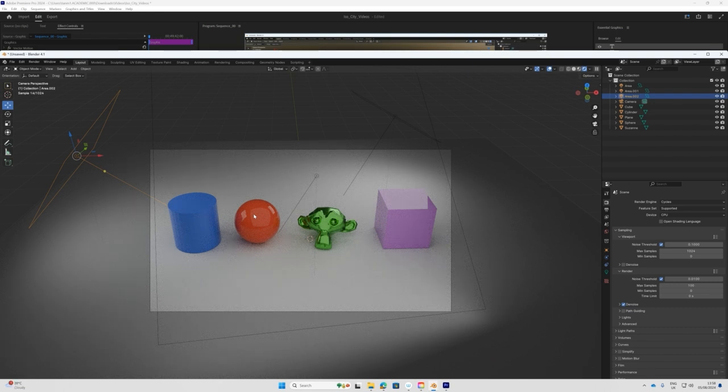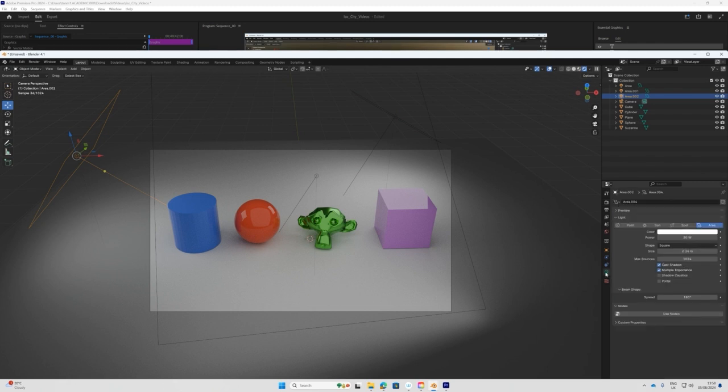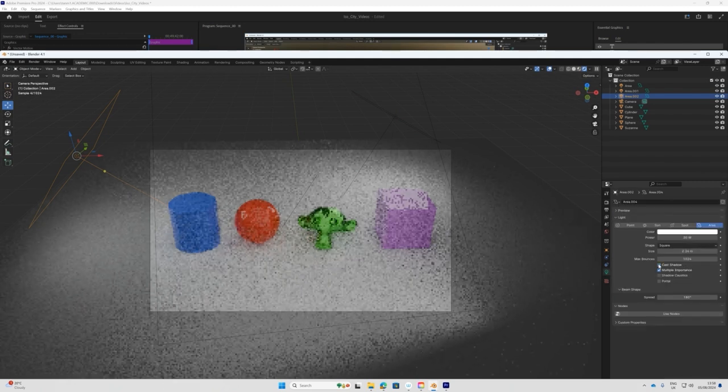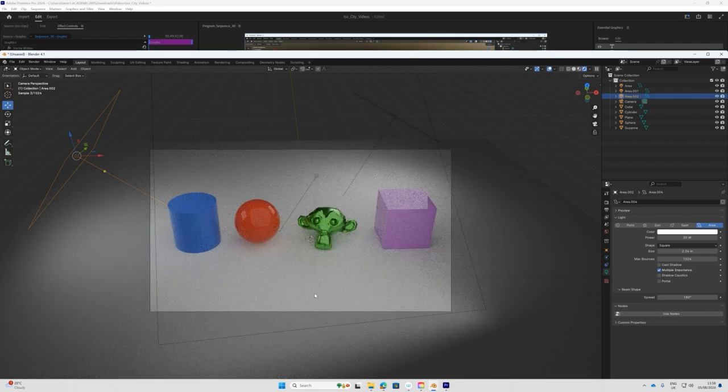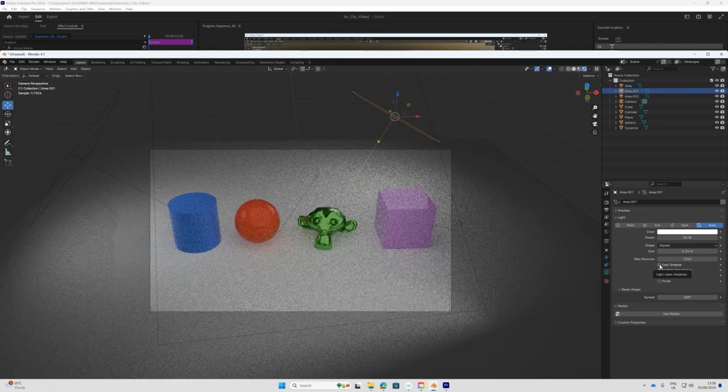So I want to make sure that I don't cast shadows from every light. If you select the light, for example, this light here, that was selected, then my last one, I don't want to cast shadows, so you can come here and click on the light and then untick cast shadow. So I just want a shadow from this big light that I have here. And I don't want any shadows from the back one either, so I can untick that. Okay.